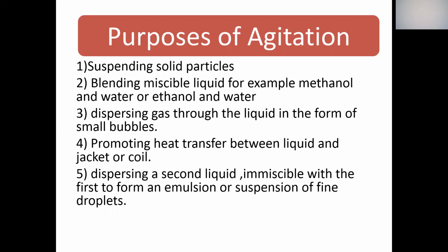Now we came to know mixing is different. We came to know mixing and agitation are not the same. But what are the purposes of agitation? Why do we have to do agitation while mixing, or what are the benefits when we provide agitation in a mixing vessel? First of all, suspending the solid particles. If you have a mixture of particles in a suspension, then when you agitate that mixture, the particles which have lighter density will suspend, and that's how it can be very easy if you want to separate out those particles from the mixture. So suspending the solid particles is one of the purposes of agitation.